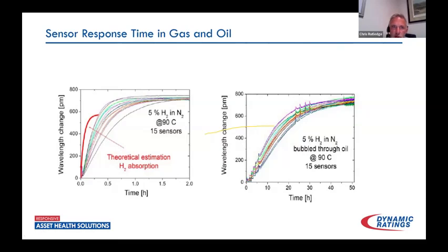So this is also done in a very well sealed, controlled environment. And we all know that if we have transformers, we do have leaks. So that's another thing that's going to factor in. Now, not to say that those drain valve installations aren't effective, because I've got several graphs I'm going to show you in coming slides where there were actually some saves done with these, but it's just something to consider. And again, it's going to go back to how do we set our alarms up, and I think that's the true key to doing this hydrogen monitoring.